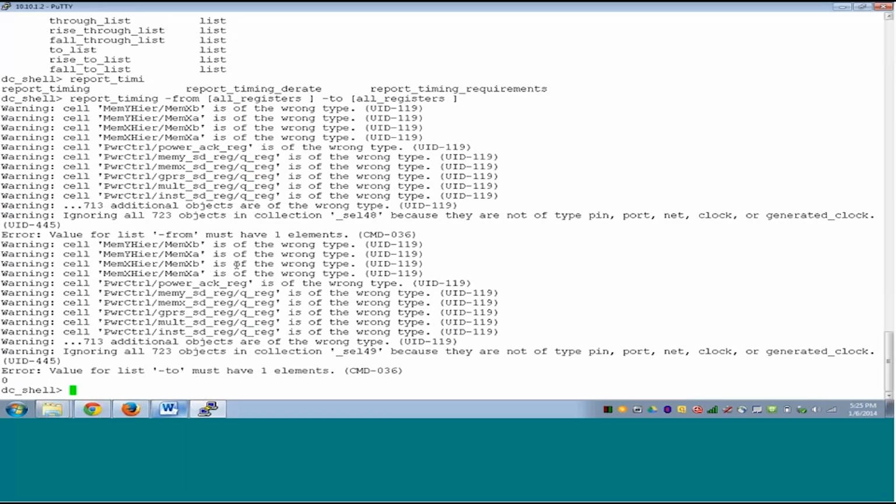The PrimeTime design timing. The PrimeTime timing engine means the software that will do all the delay calculation and will show you the timing report. The PrimeTime timing engine is much more superior to Design Compiler. Design Compiler commands for timing are very basic versions of that.